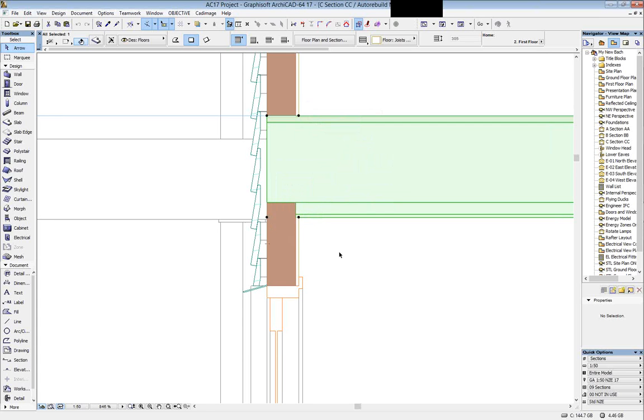So it's giving us the ability to create these very nice general arrangement section views which need very little extra input. For us to do this in ArchiCAD 16, we probably would have used 2 slabs, one for the floor and one for the ceiling, but we can get away with just a single element in version 17 with the correct priorities. And as I said, this is standard ArchiCAD 17 we're looking at now, so hopefully we've got the priorities all sorted out and working well.